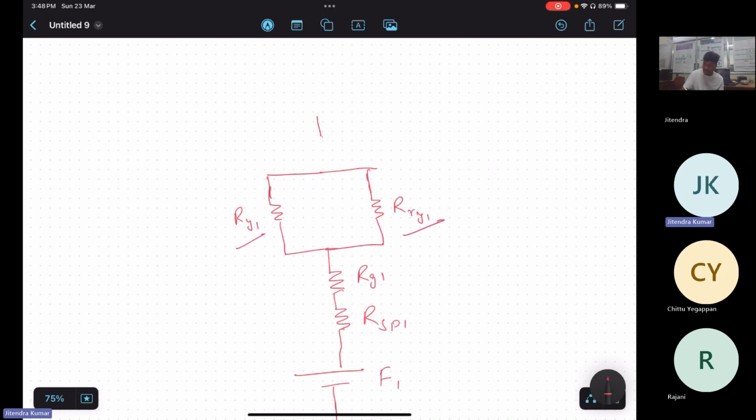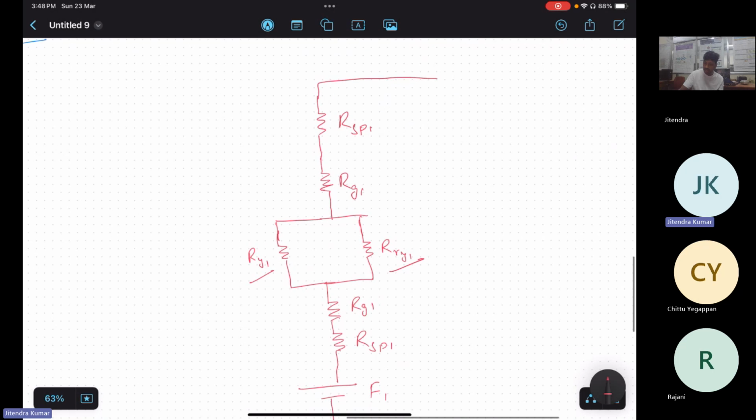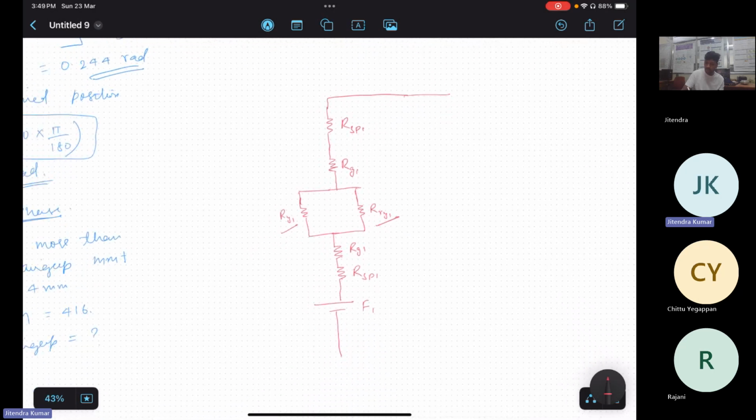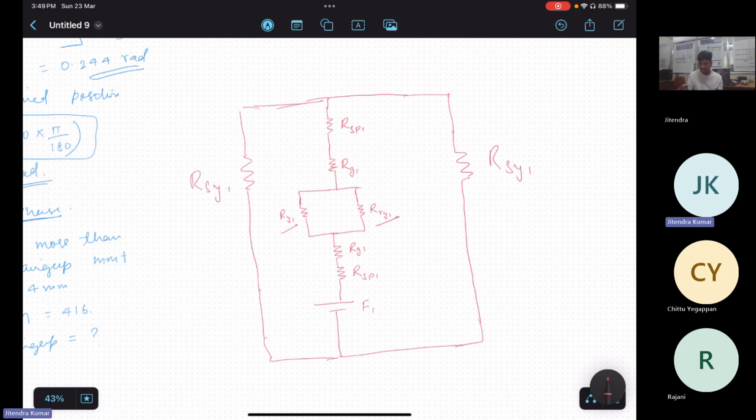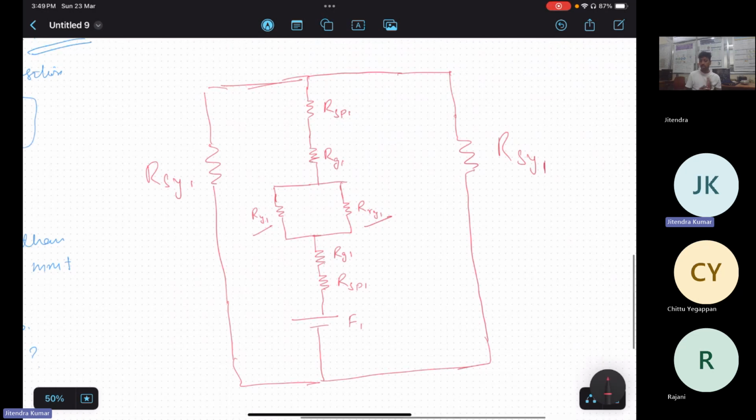These two are for the rotor back iron, and after flowing through the rotor back iron and rotor teeth, it will go to the air gap again. Then again it will cross the air gap and now go to the stator pole. Okay, now the stator back iron will also be covered twice, or basically flux will be divided in two directions like that. SY. There is no need to write 1, because it is just a notation of one part or one pole we are drawing it for.